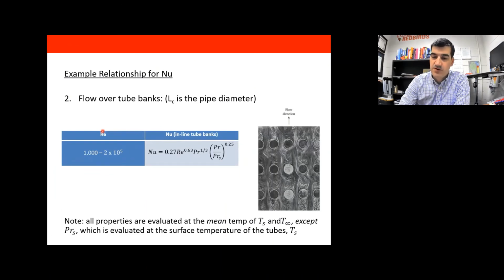There's one more situation that I want you to be able to calculate. This turns out to be very relevant for boilers and condensers, because in boilers and condensers, we've got lots of small tubes that are going through the boiler or through the condenser. For example, in the condenser, we've usually got cold fluid, like the lake water from Clinton Lake, going through the middle of the tubes.